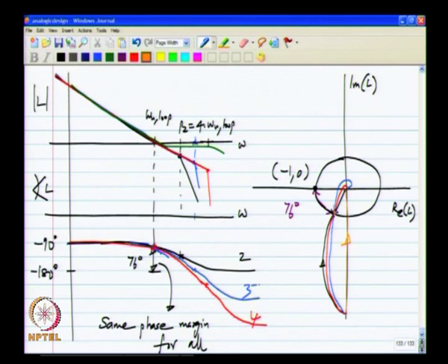Okay. So, for this you have to design the system for a particular phase margin, and that is why it is useful. Okay. Now, one more note about this phase margin. So, from our investigations we said that phase margin of 60 degrees or more is good, but this is not a sacred number. This assumes that the overshoot is an important criterion in the step response of the system. There may be cases where you can tolerate a little more ringing and a little more overshoot. So, there phase margin of 30 degrees may be adequate. So, we will not talk about that as a general criterion, but in specific cases maybe a phase margin of 30 degrees is adequate. Okay.